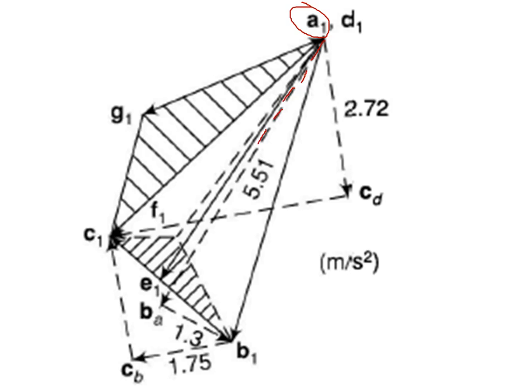Don't concentrate on the entire figure, just see what I am taking with this red color lines. So you will be getting parallel to A1 BA in this manner. So you will be getting a parallel to link AB and you will get a 60 degree angle in this manner, and you take it as 5.51. You know this value 5.51. So take a suitable scale.